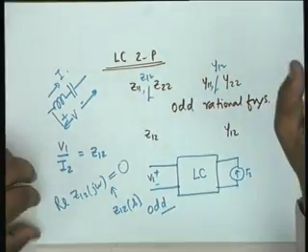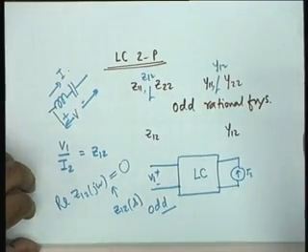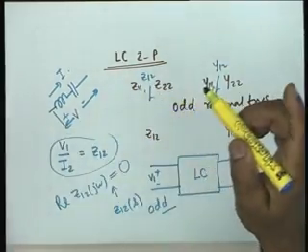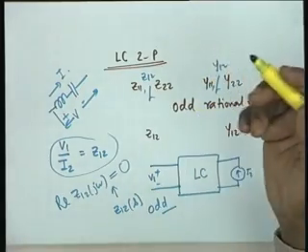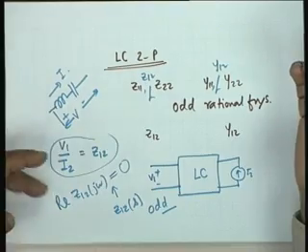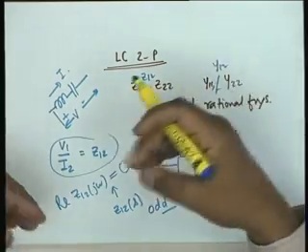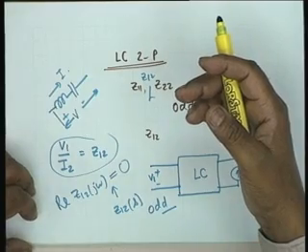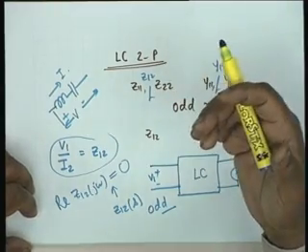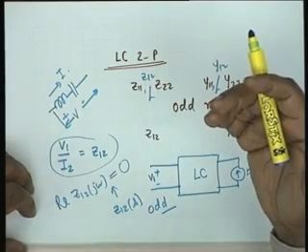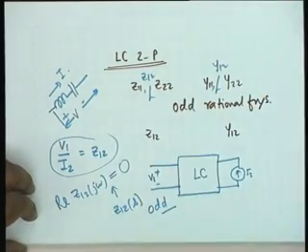We are not talking of poles or zeros. We are talking of frequencies at which the ratio is neither a pole nor a zero. At that point, the voltage and current measured anywhere in the network shall be 90° out of phase. And if you consider this a challenge, construct a counter example. All right, that I leave to you.